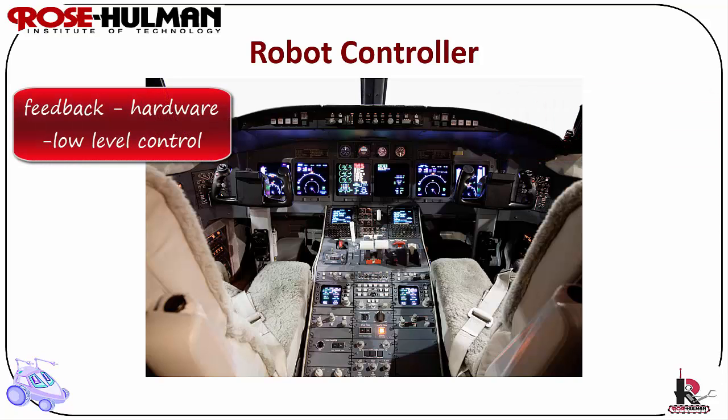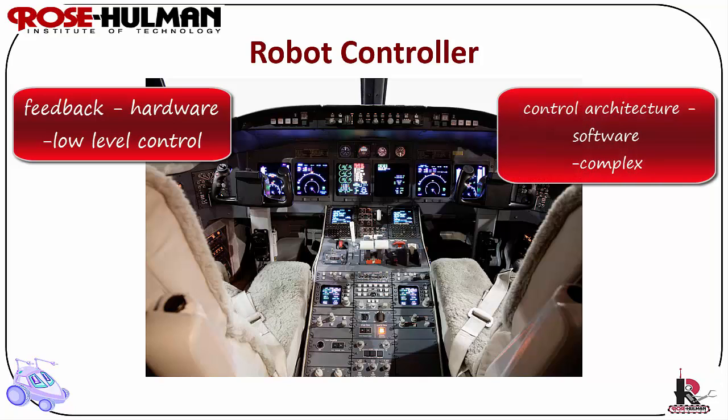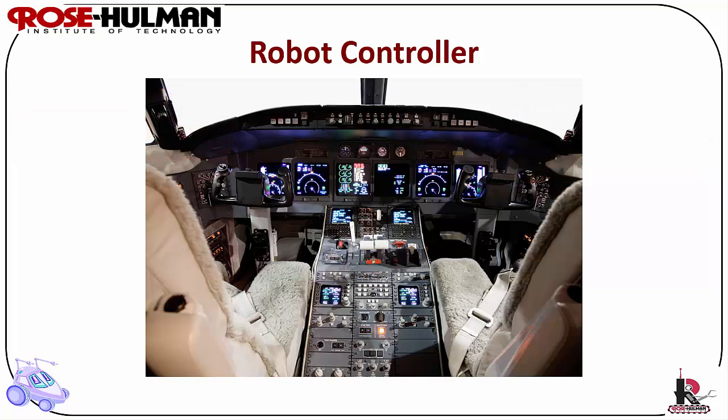Feedback control is good for low-level control of actuators, such as wall following or obstacle avoidance. More complex controllers are typically implemented in software. Complex tasks require a control architecture, such as localization, object retrieval, mapping, path planning, etc. A robot control architecture provides the guiding principles and constraints for organizing a robot's control system, i.e. brain. Solving a problem using a finite procedure is called an algorithm.